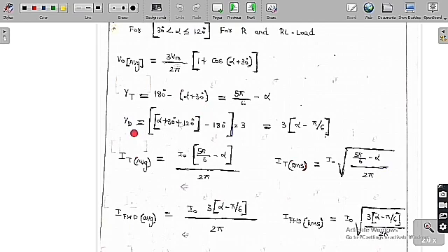So the conduction angle of the diode is equal to alpha plus 30 degrees plus 120 degrees minus 180 degrees, into 3. So alpha plus 30 means, I am trying to find the range for T1, which is alpha plus 30 plus 120 minus 180.